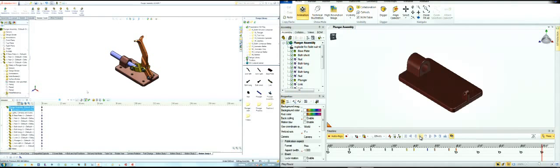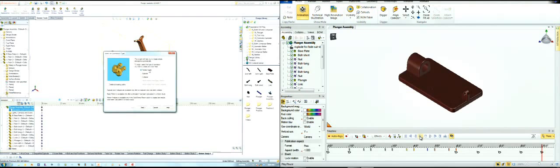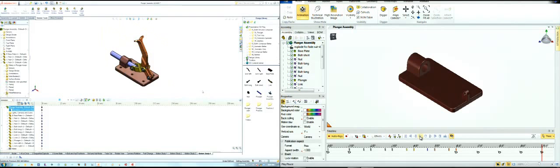Okay, on the SolidWorks side, many of you know we've got a wizard. We could go in and do a rotate model. But the bad news about rotate model is it rotates about the screen. So if you tell it to rotate about the y-axis, it's going to rotate it about the y-axis of your screen, not the model. But that's not a problem. I can do this a different way.